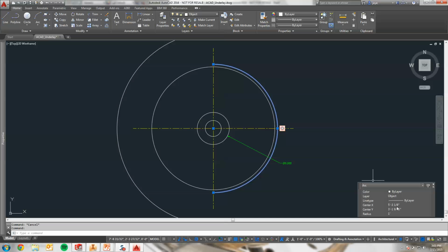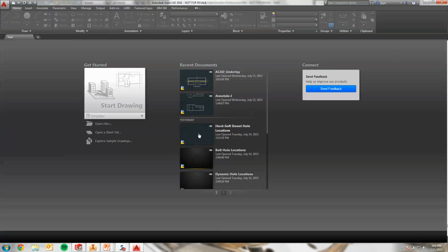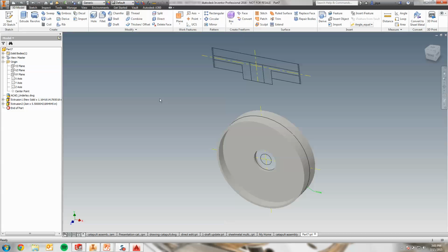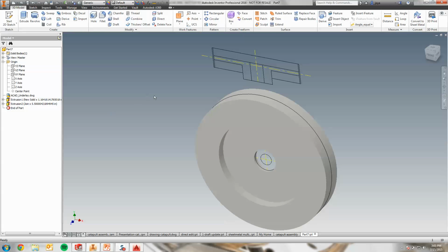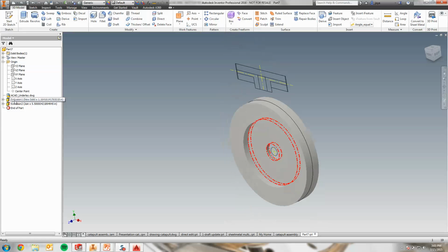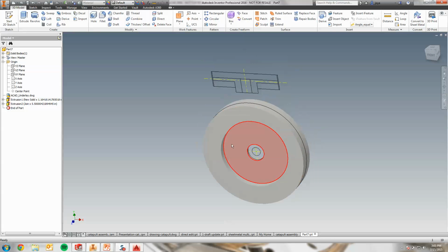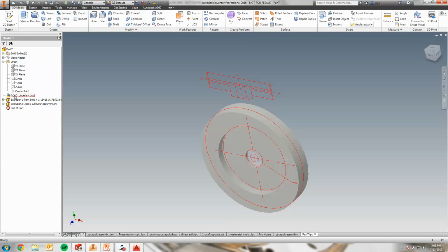That one. Let's do this side. Again, I'll do 1.5 feet, like so. Save that document. Just go ahead and close out of it. Bring Inventor back up. Now there's a lightning bolt in my quick access toolbar, and lo and behold, my first extrusion has now updated with that DWG underlay. So I can drive the shape of my 3D part in Inventor off of just that AutoCAD underlay. This is part of the AutoCAD technology.